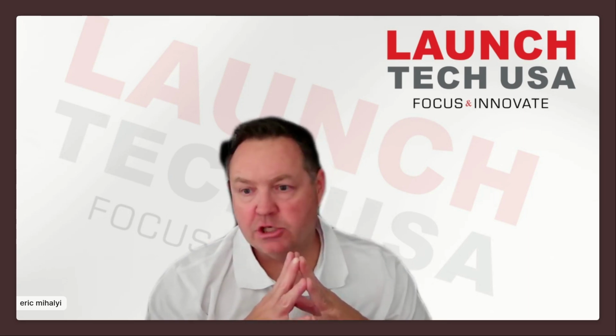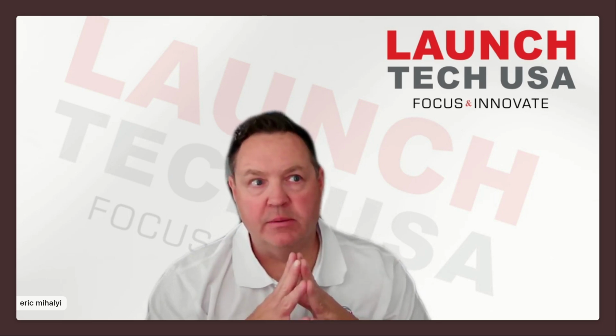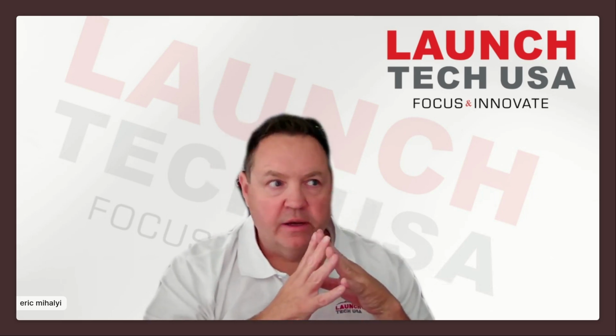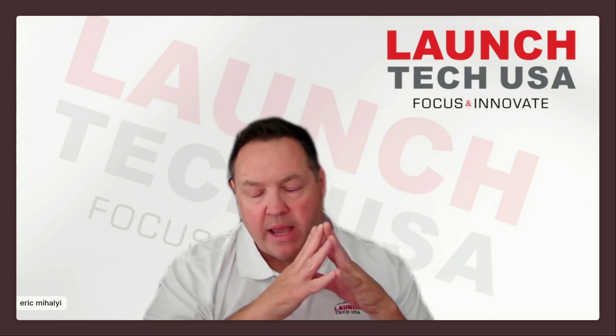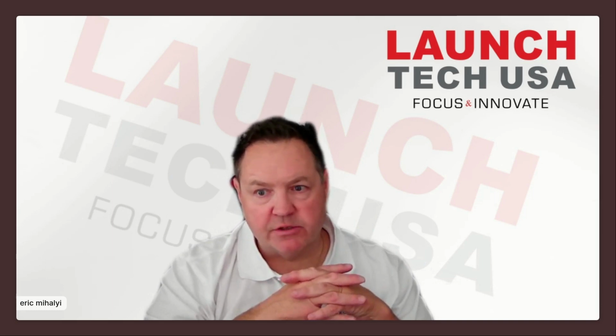So that gets you in the diagnostic arena you need to be in faster, right? You're not going to be chasing. I probably don't want to look for a misfire. I probably don't want to start getting into spark and fuel. I probably want to try and maybe do a relative compression test or something.